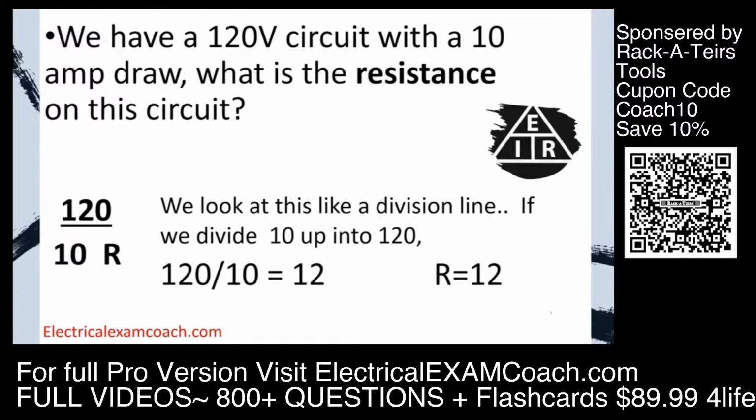Then all I have to do is divide. I divide 120 by 10, and it lets me know that there should be 12 ohms of resistance on this circuit. Meaning I should be able to put my amp clamp out and read 10. I should be able to put my voltmeter out and read 120. And I should also be able to measure the resistance and measure 12 ohms. If I don't have that, there's something wrong. There's something failed, there's something broken, there's something disconnected, there's something causing more resistance that's gotten in the circuit.